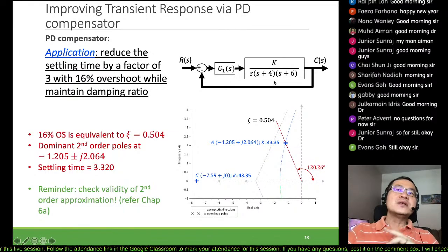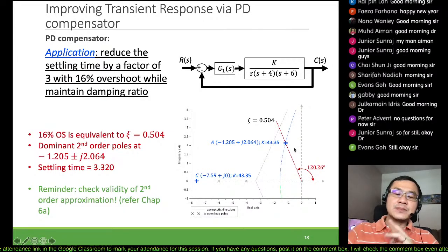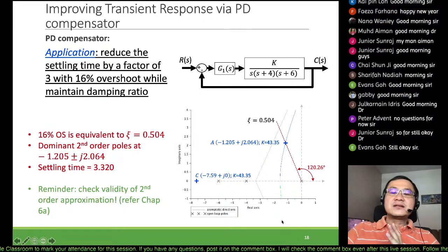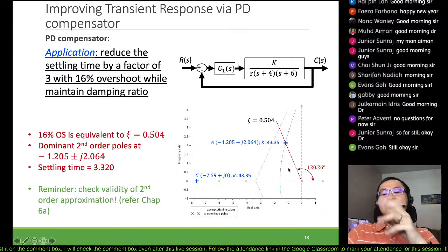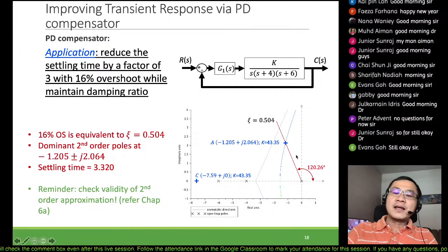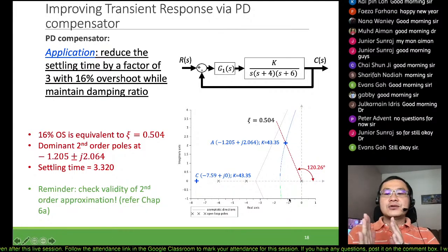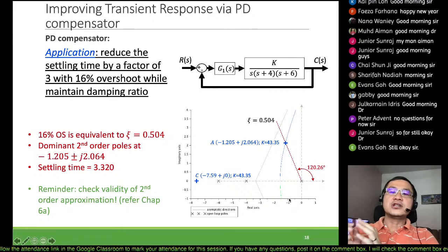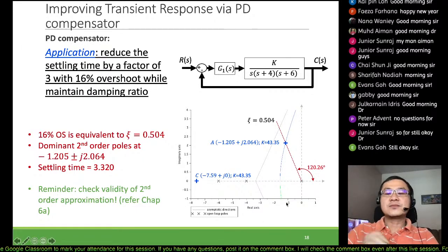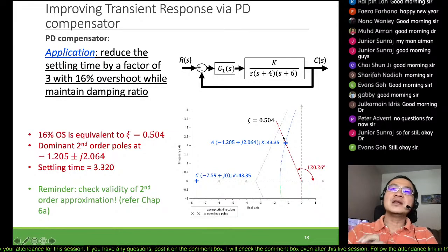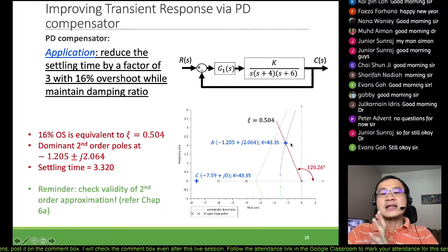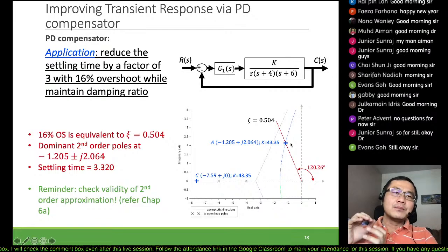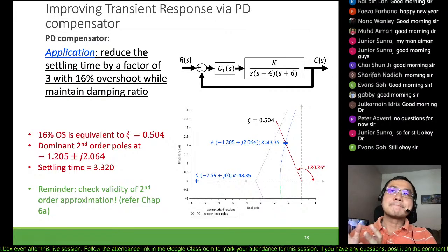Why we always treat it as a second order system is because we would want the poles, which usually are only 2 points, a conjugate pair of complex poles, close to the origin. Okay, when these 2 points are close to the origin, we call them dominant poles or dominant solutions. And our system actually behaves based on these dominant poles.